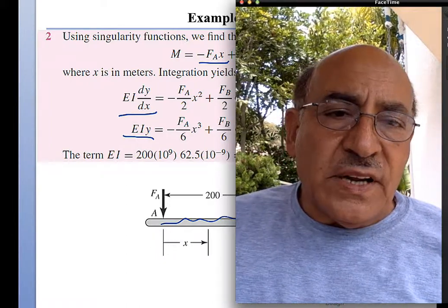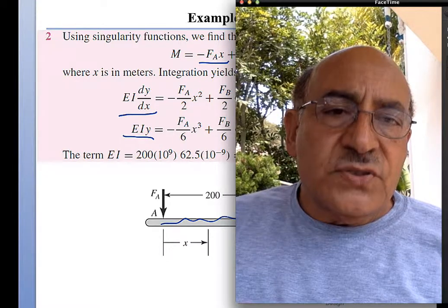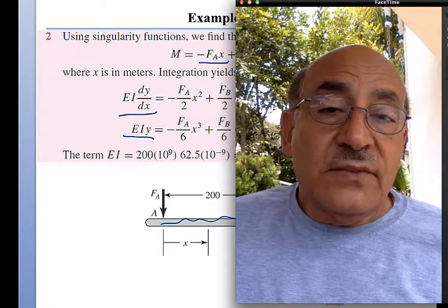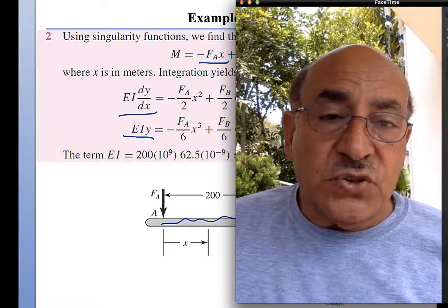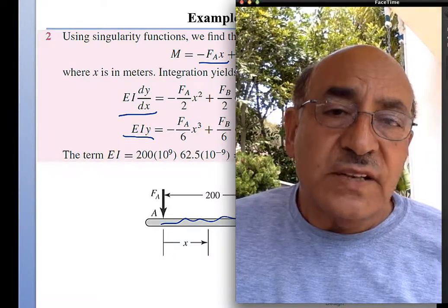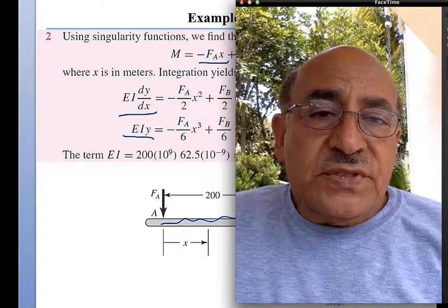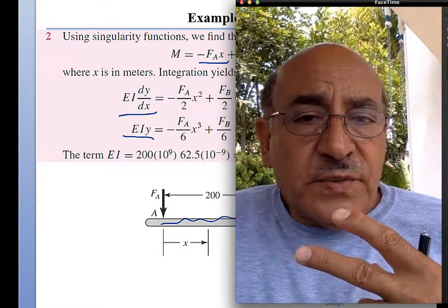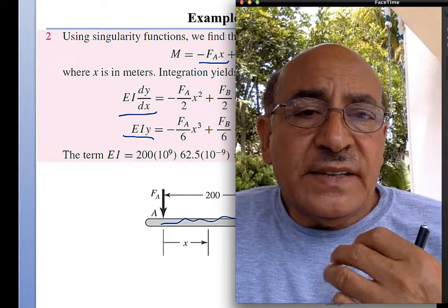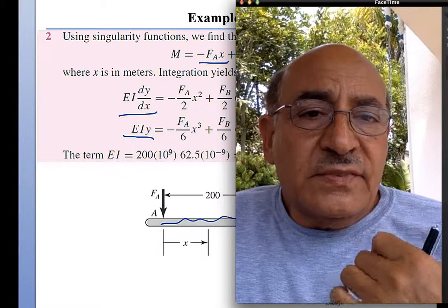I added two more unknowns, C1 and C2. So now I have to find 5 equations instead of 3, because I had already 2 and I was looking for another one, but I ended up introducing 2 more, which means that I got 2 from equilibrium, then I have to find 3 from deflection.